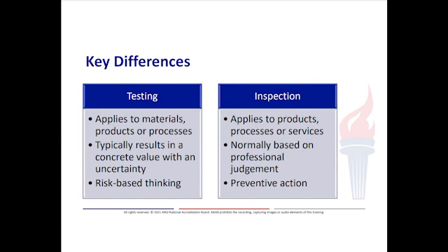When these pressure vessels are put together, they have to have certain steel that's been tested and has test results to it. They also have to have weld inspections that are performed. These may be radiographic inspections, they may be visual inspections. These all have to be performed in a specific sequence because as you seal up a pressure vessel, you can't go back in and do a visual inspection on the welds. You can't go back in and do a radiographic inspection on those welds. You have to do it as part of this process.